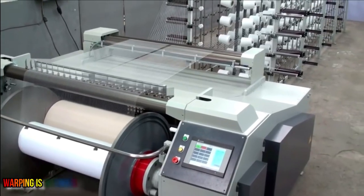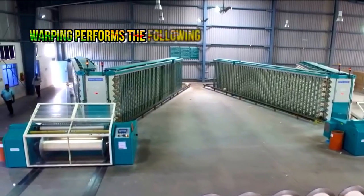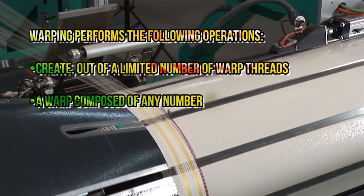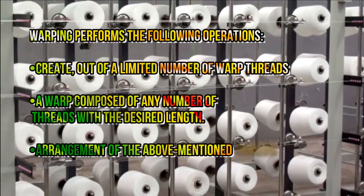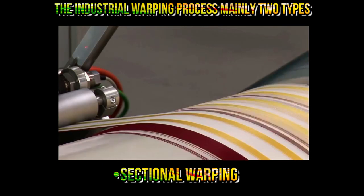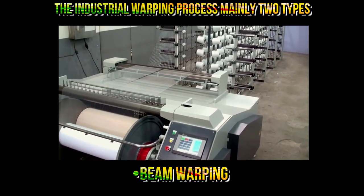Warping. Warping is intended to prepare the beam of the weaver to be installed on the weaving machine. Warping performs the following operations: create, out of a limited number of warp threads, a warp composed of any number of threads with the desired length, and arrangement of the above-mentioned threads according to the desired sequence. The industrial warping process can be accomplished by sectional warping, conical drum or indirect warping, and beam warping or direct warping.